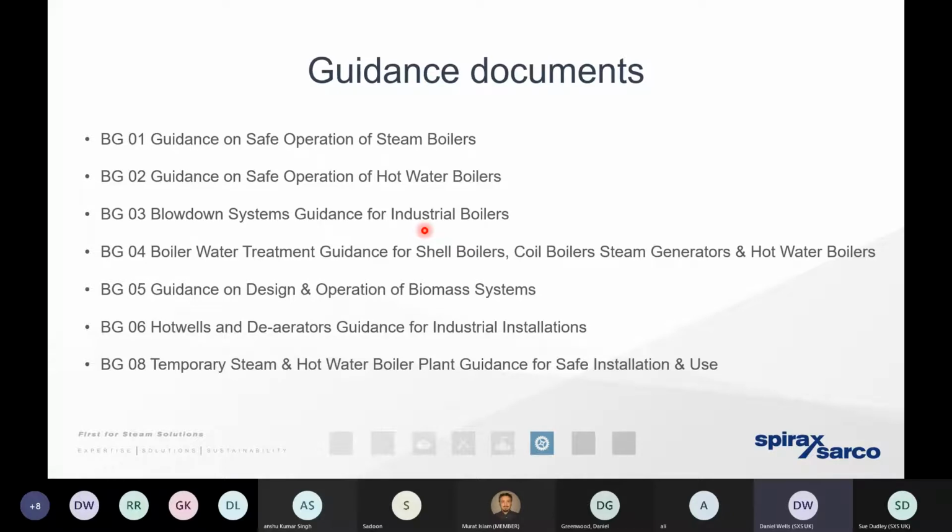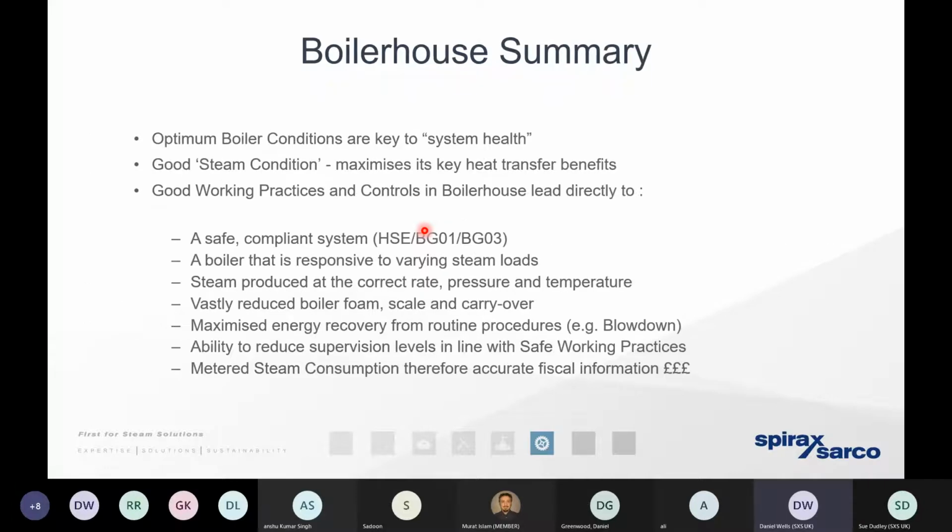So it's for that reason that there are so many different boiler control types. It's for that reason that there are so many different level control types, that there's an on-off pump and a modulating pump alternative. It's for that reason that we could choose to blow the bottom blowdown manually, or we could choose to upgrade and retrofit a timed actuator onto it so we can do it automatically. It's for that reason that we could remove the TDS from the boiler manually, or we could choose to do it automatically by using a conductivity probe ahead of a modulating valve.